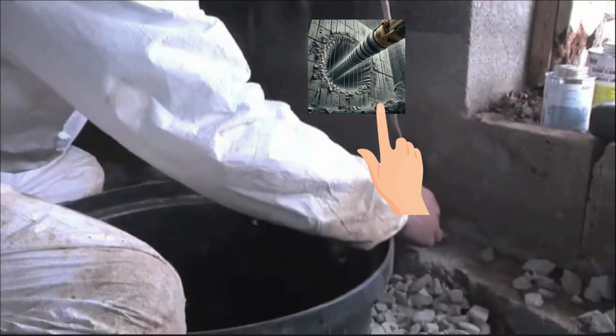Next, we will use a concrete core drill and bit to drill through the foundation wall. Make sure the drill bit is the correct width for the drainage pipe to fit through the newly drilled hole. Use caution to make sure you don't drill into any foundation areas with existing pipes. Looking on the outside of the wall should confirm if utilities are present in the area.